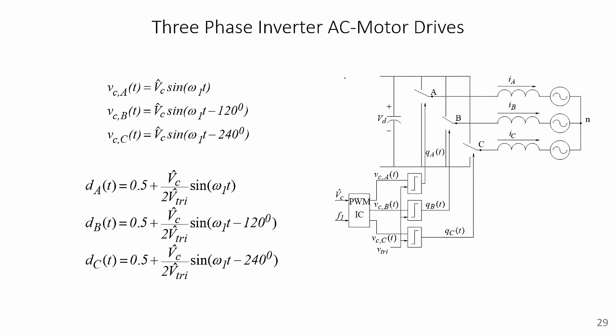The full bridge converter can be extended to a three-phase two-level inverter by adding one more switching power pole to the full bridge converter, as shown in this image. Instead of using a constant modulation signal as was the case for DC drive, we can adjust the modulation signal to follow the profile of a sinusoid to generate sinusoidal output voltages.